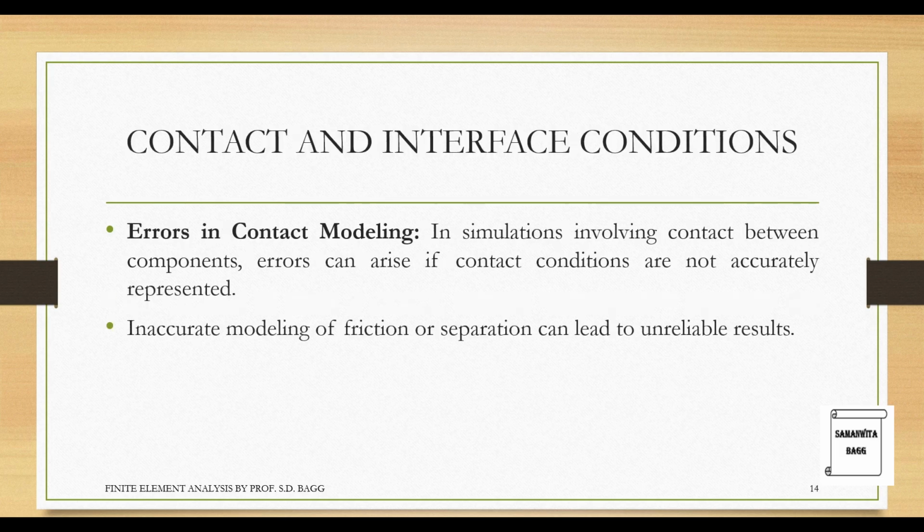Then comes contact and interface conditions. In simulations involving contact between components, errors can arise if contact conditions are not accurately represented. Inaccurate modeling of friction or separation can lead to unreliable results. So you need to give proper interface and contact conditions in FEA.